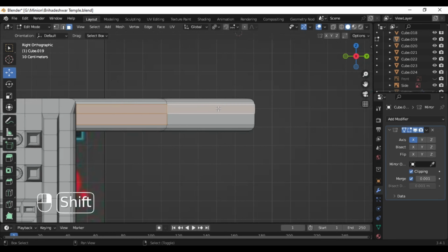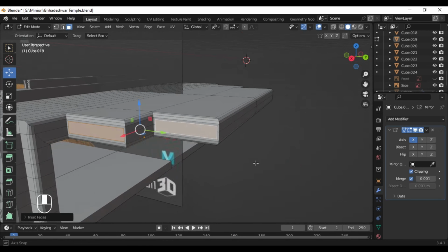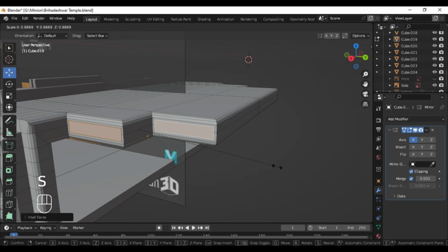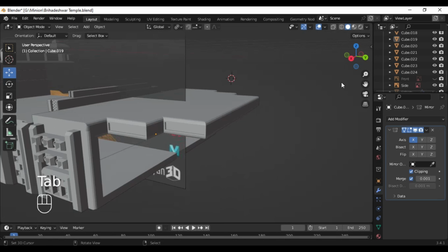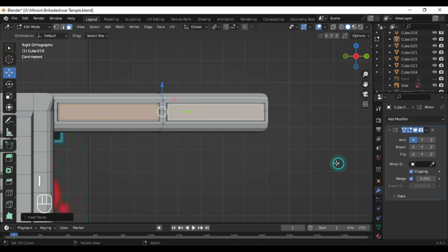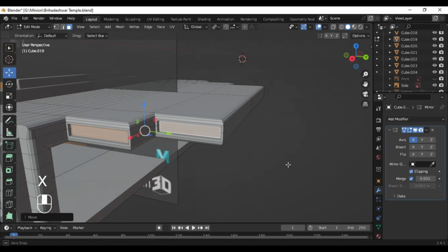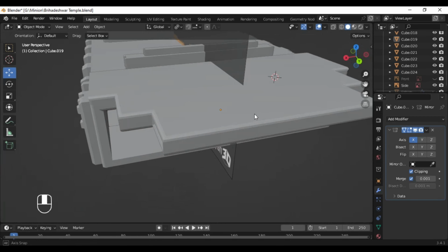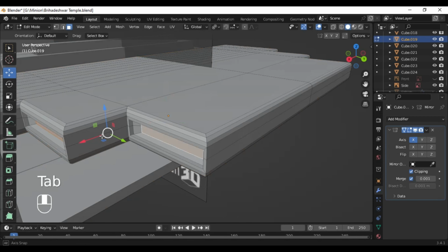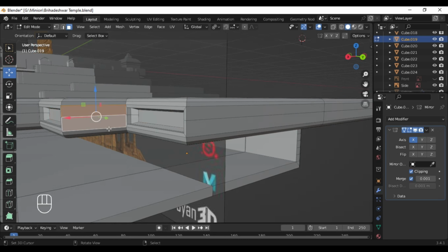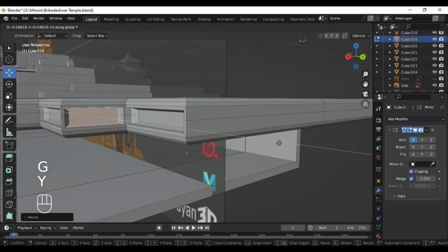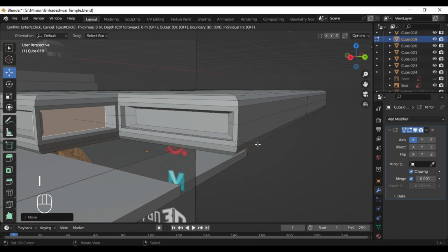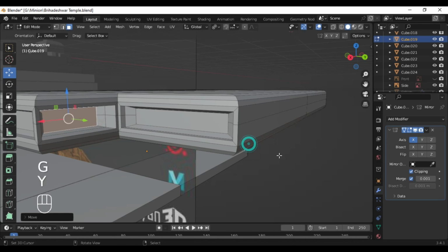So once the beveling has been done, I am selecting these faces and turning them into a dissolved one. I mean, turning it into one face, and inserting the face and doing the same process of making a cavity into that object by using a couple of inset faces and then moving them in their respective inverted direction. So you can follow this same process throughout each of these, I mean inserting the face and that kind of thing.